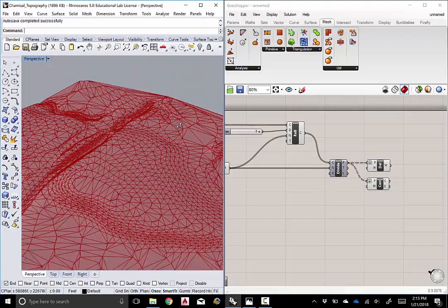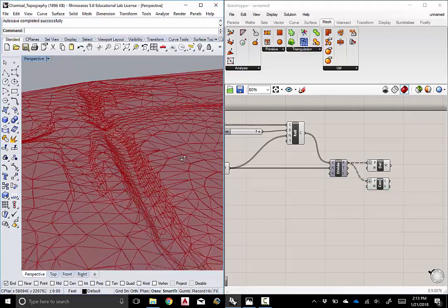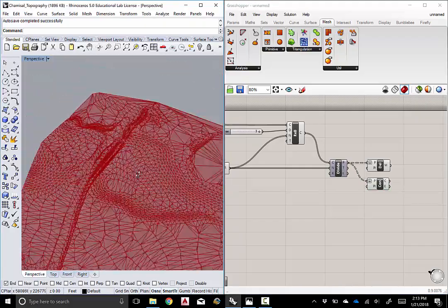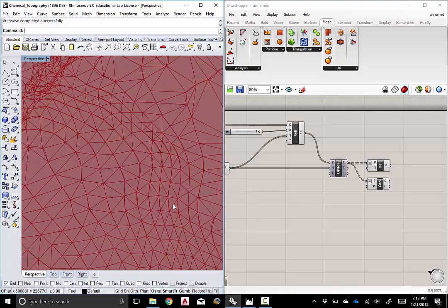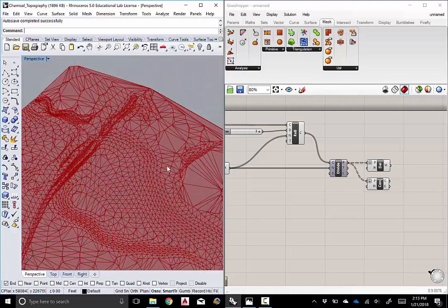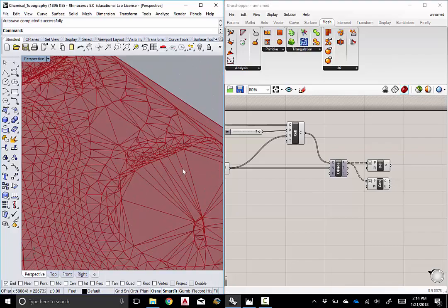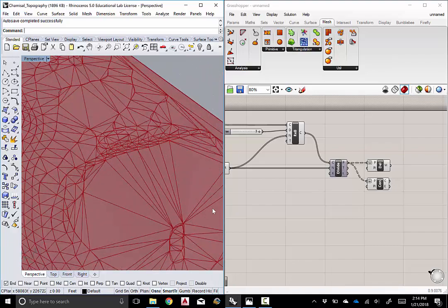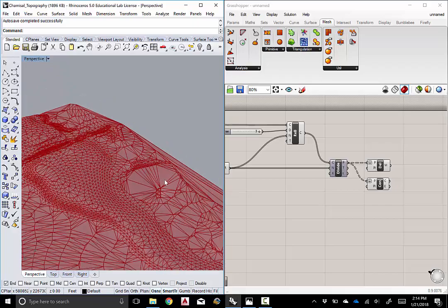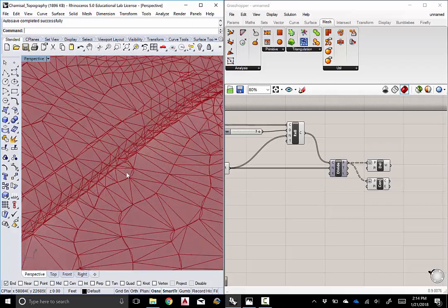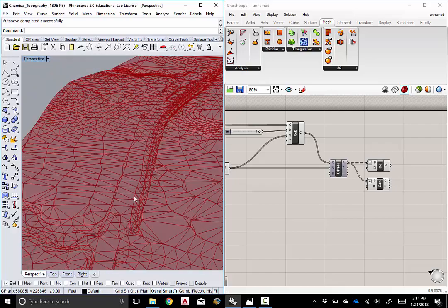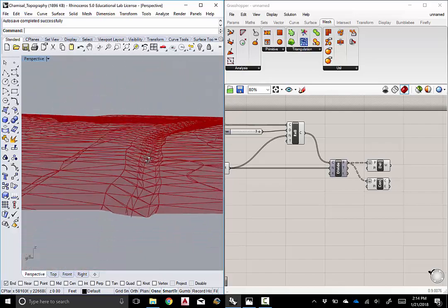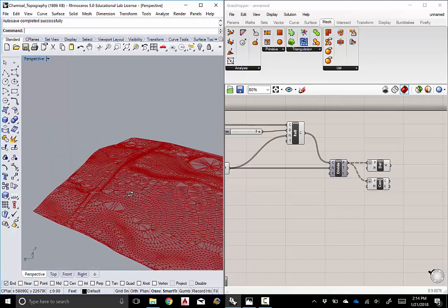This gives me a better understanding of the shape of this surface, and I can see that on one hand I have fairly similar sized triangles making up this mesh, which is good. It's a nice even mesh, except for of course places where that's just not possible, like these low points here. And I also don't have any kind of meshes with intersecting faces, and you can just sort of scroll around and look to see if there aren't any problems.